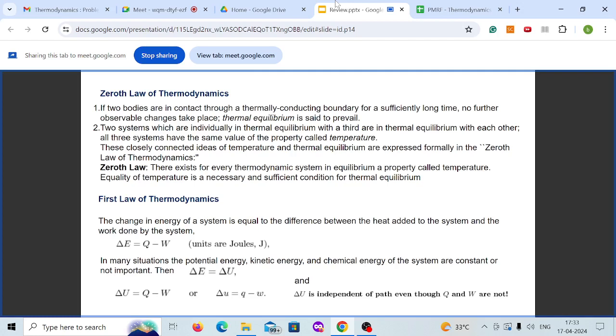This temperature will be equivalent to your ambient temperature. If it's not insulated, that temperature will be equal to your ambient temperature. So that pressurized cylinder is in thermal equilibrium with your ambient surroundings. But if you see, the states of the system and the surroundings are different. So even though these are in thermal equilibrium, these two systems are not identical. That you should keep in mind.